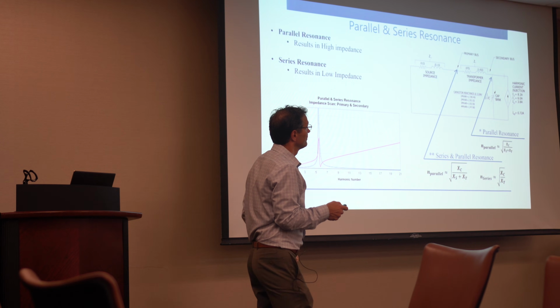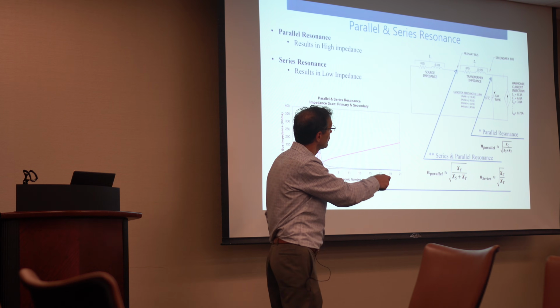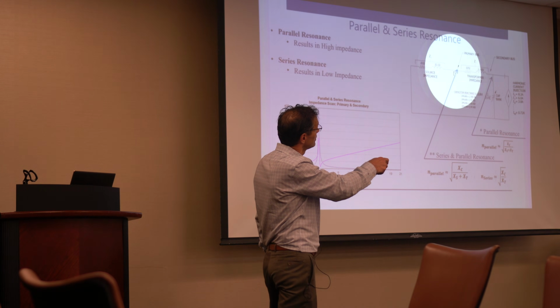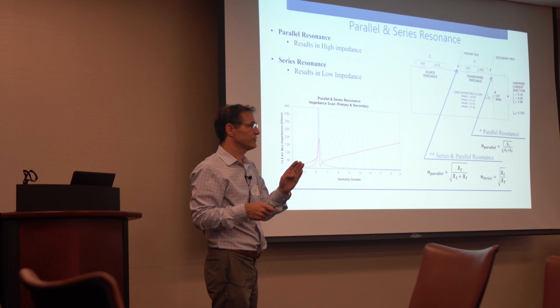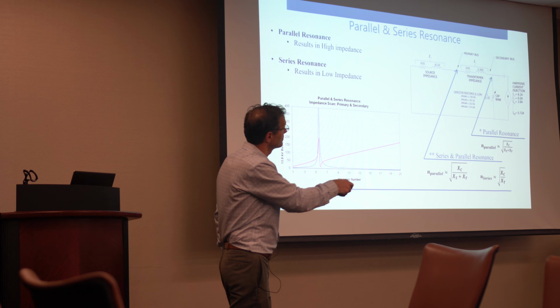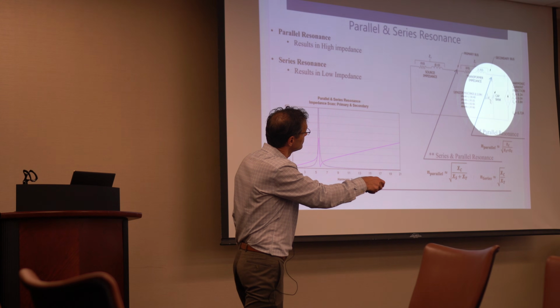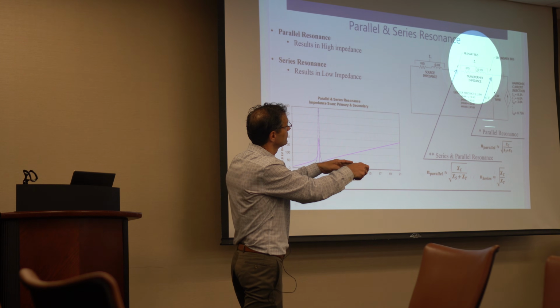For the most part, this resonant point from this location doesn't matter too much. But what you often see is when you have low voltage capacitors, 480 volt, and I'm on a medium voltage network, this might be a low voltage capacitor bank, behind a step down transformer from 13.8 kV down to 480.